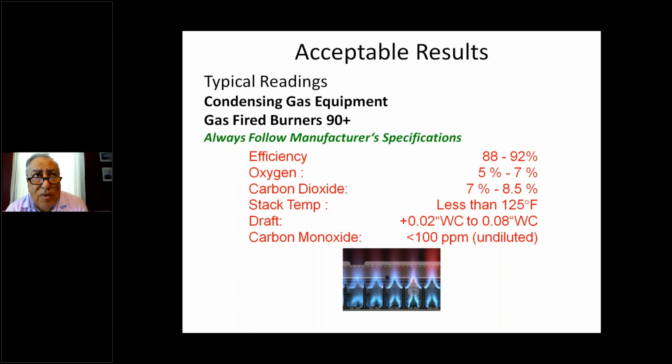Chimneys are natural draft appliances, and chimneys are going to draw simply because warm air or flue gas rises a lot faster than cold gas. So warm flue gas rises and moves through the appliance. A draft regulator works by opening and closing. It's barometric, depending on the amount of draft moving by it.